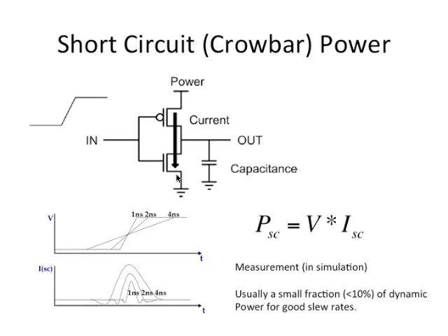But when the output is discharging, I'm turning off the PMOS. Initially it is on, it's turning off, but for a short duration both PMOS and NMOS are on, so there will be some current. The term to use here is not leakage but short circuit current, because I'm shorting the VDD and ground. I'm shorting the power and ground here, so there will be some short circuit current.